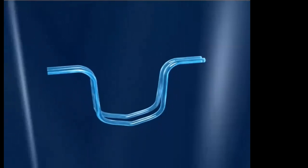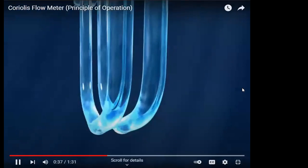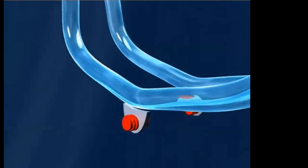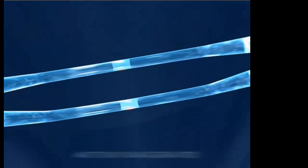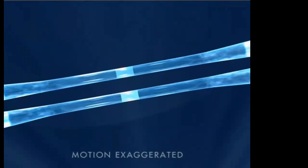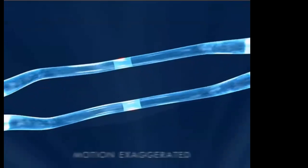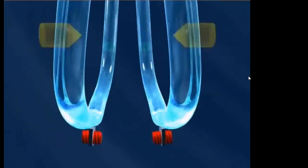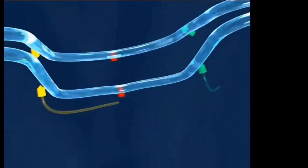For practical exploitation of this principle, it is sufficient for the 2 measuring tubes to perform oscillations on a small section of a circular path. This is achieved by exciting the measuring tubes with an electromagnetic exciter in its first resonance frequency. When no mass is flowing, the two tubes oscillate symmetrically. But when a mass flows through, the tubes deform proportionally to the mass flow rate. This deformation is registered by two sensors and forms the basis of the measuring result.